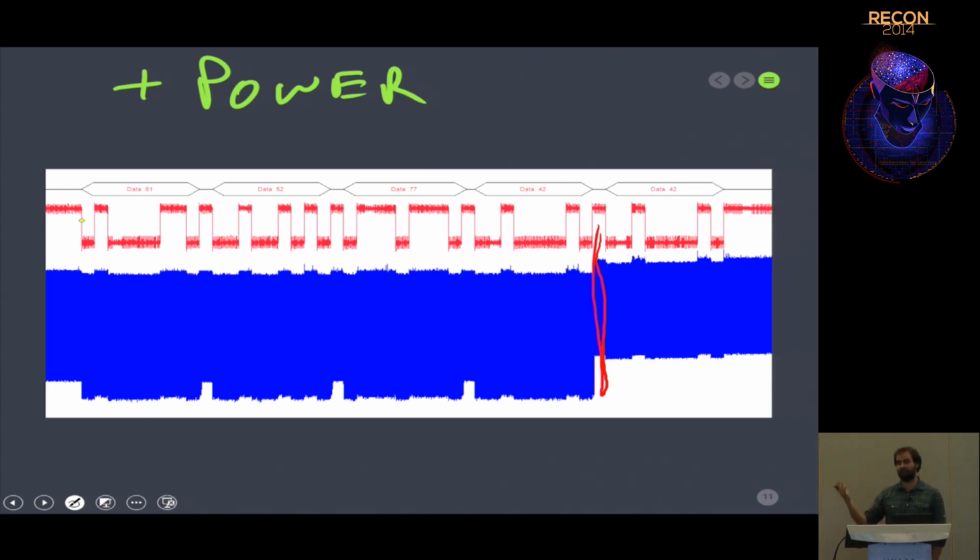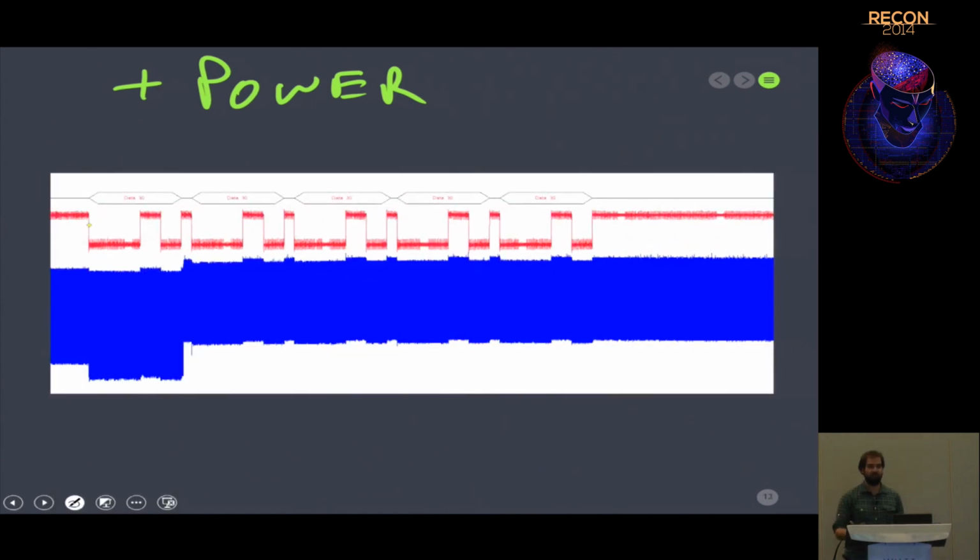So you can see immediately where your password is wrong. So again, in this case, you script it to try every combination for the first byte, and as soon as it sees that this power level goes here, it knows the first byte's wrong, and then it keeps doing that until it gets the full password. So that's sort of what's generally called simple power analysis. So we're using the power of the device to learn just a little bit about what it's doing.